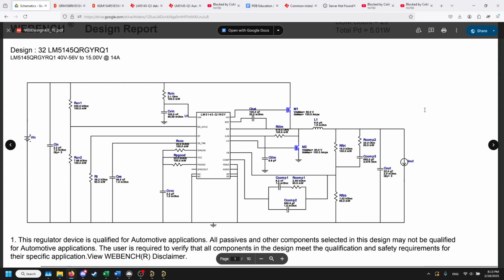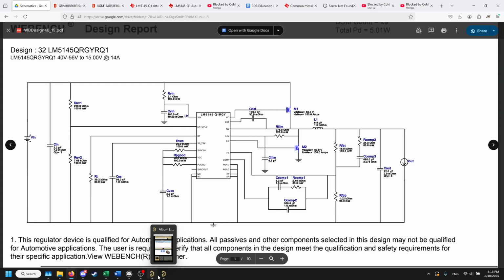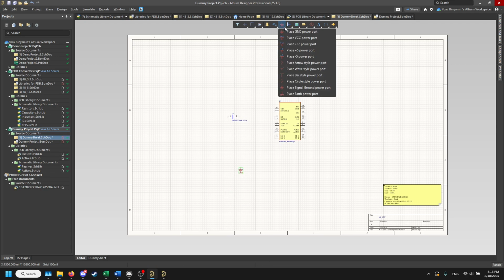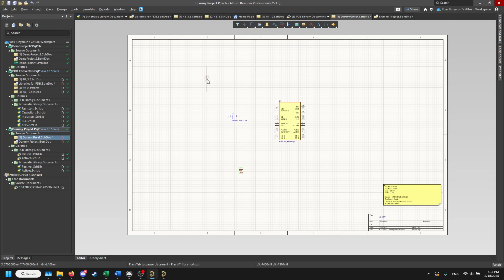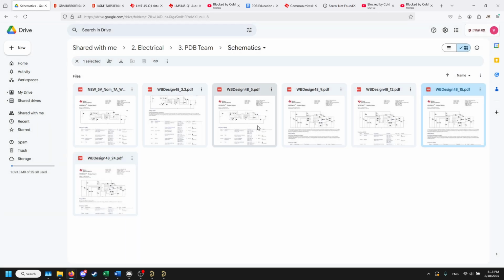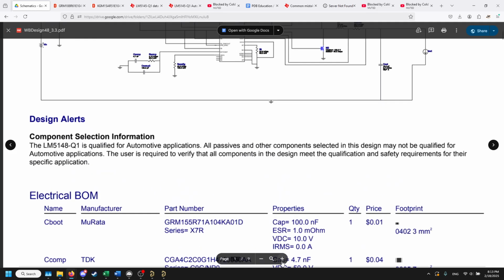And then you have a ground, which should always be facing down like this. To import a ground you just place this kind of object, and then you can place the power port like VCC, and this should always be facing upwards. Okay? And then I'll show you how, let's say, the 3.3 looks, which I made a little earlier.